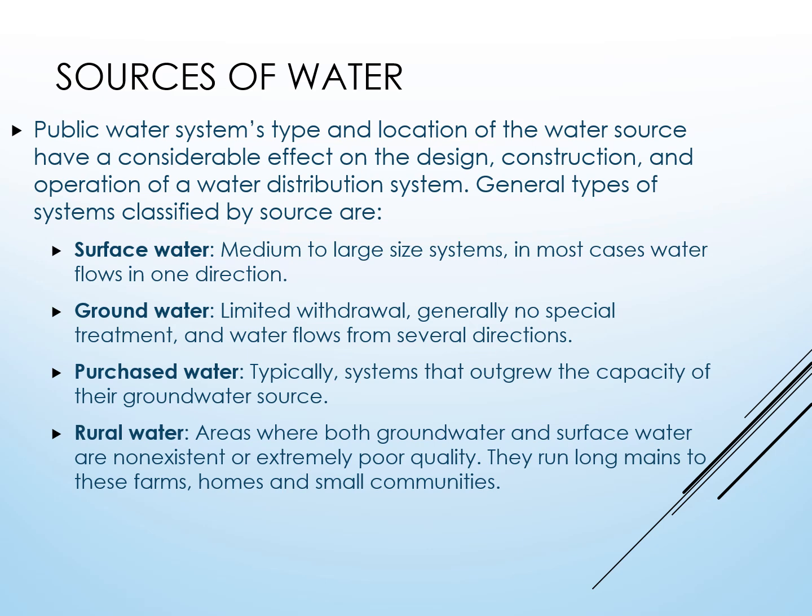You're going to want to understand sources of water, understand where your water is coming from. It's just as important as some of the math that we're going to be doing, because the source will also dictate the treatment method. It will dictate how much you're likely to have. A lot of times you're going to find that surface water is used to treat large systems, and groundwater is relatively limited in its capacity, just due to recharge rates.